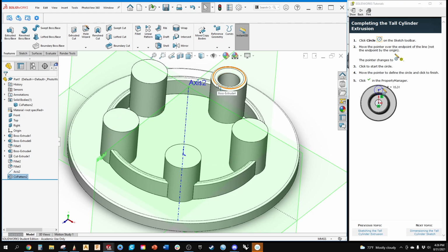But the radiuses aren't there. The hole's not there. Because all I did was select that one command that we made. Well, I want all of it. I want this feature, which was the extrude, this feature that was the hole, and then the 2 fillets.